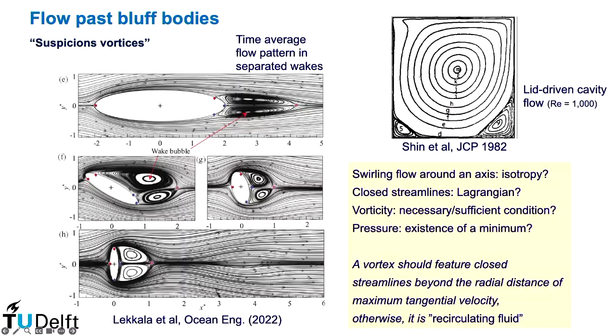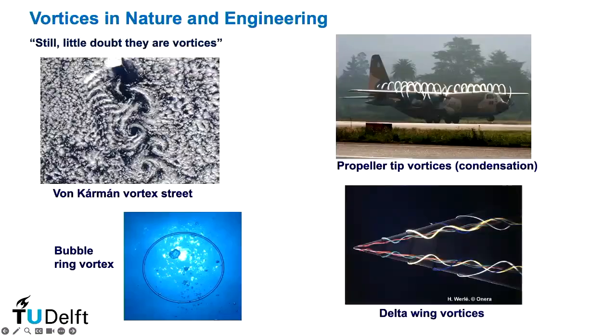My personal take on this problem, I think it was presented by others, is that I would not include this in the family of vortices, and I will explain why. Because if, after we have accepted all this family of vortices, and then we focus ourselves on vortex detectors with specific local conditions, maybe the local condition of this type of vortices is quite different from the Kelvin-Helmholtz and the Karman vortices, then we risk making our problem on vortex detection and definition even more complicated.